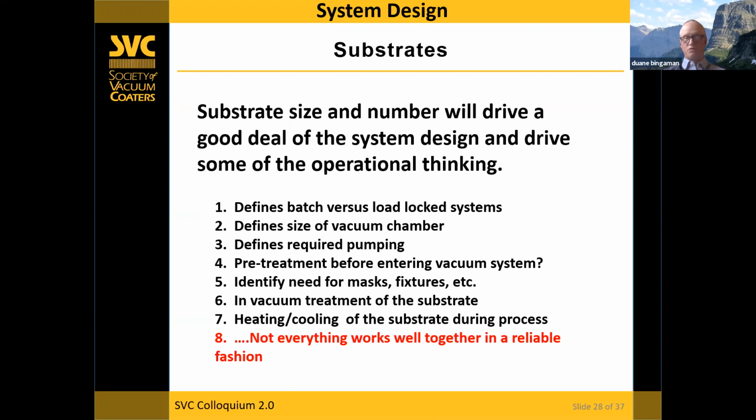We see a lot of substrates that maybe are phenolic resin that require a lot of pretreatment, and it needs to be accommodated for. There are things you can do. You can do pre-treatments like you're talking about, so that you don't have to impose the burden upon your process chamber to pump all the bad stuff out of the substrate. You can do it before it gets there if you treat it right.